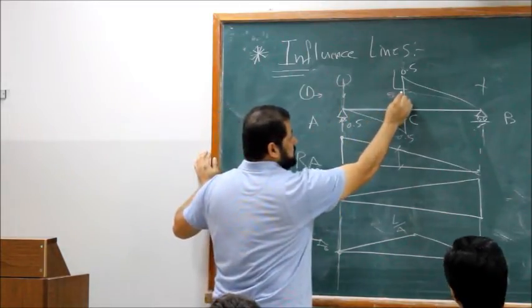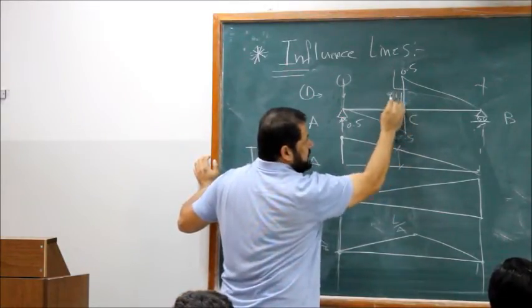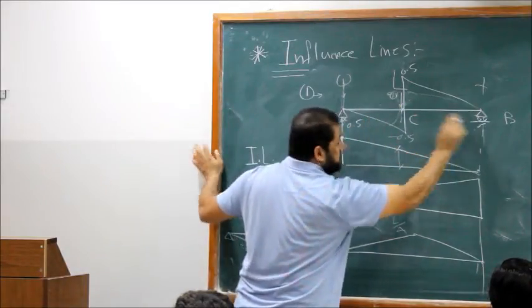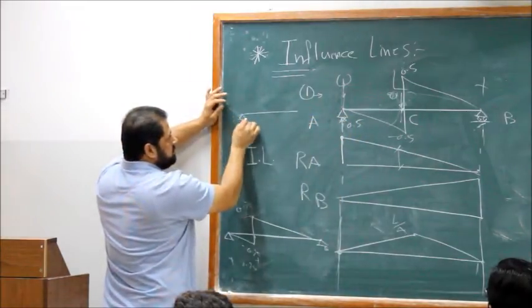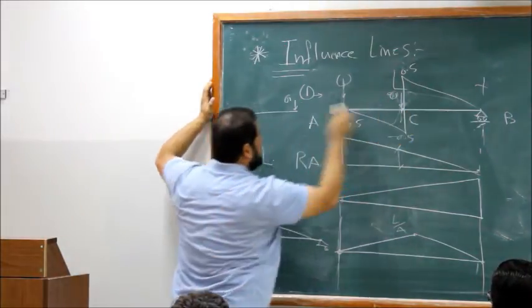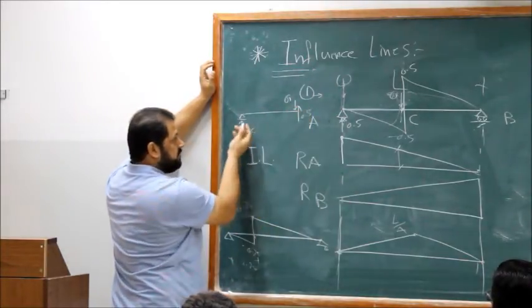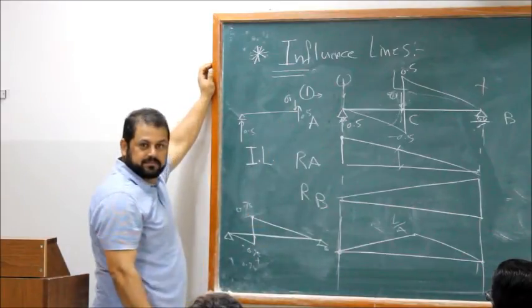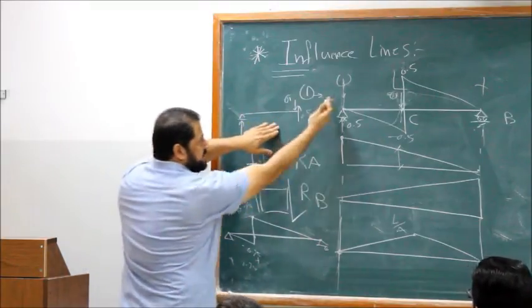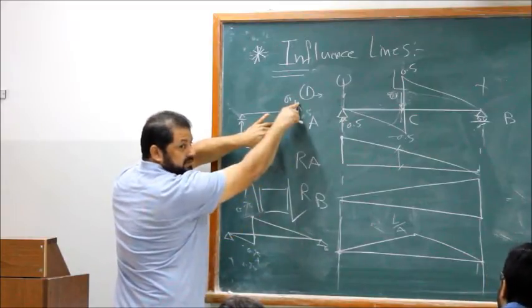When the unit load is all the way here, just before crossing, the 1 is here, right? How much is the reaction here? 1.5. How much is the reaction here? 1.5. Take a cut. This is 0.5, right? It is still in the section, did not cross C. So if this is 1, how much is this one? That's 1.5. This is a negative shear. This is a positive shear, and the opposite is negative. So on the right face, positive shear should be down. Up, so this is negative.